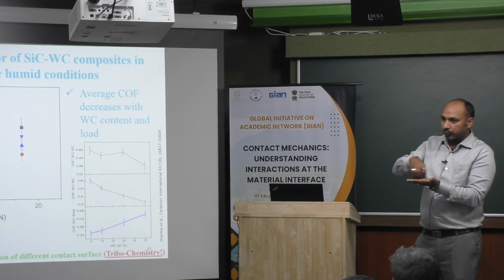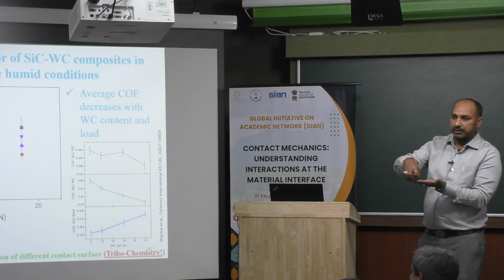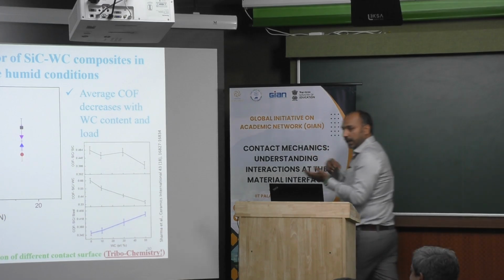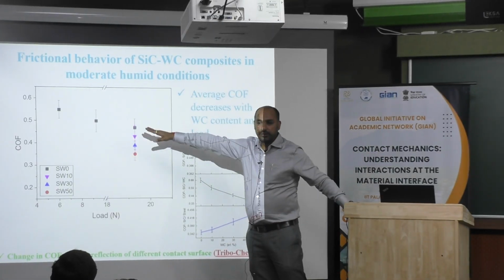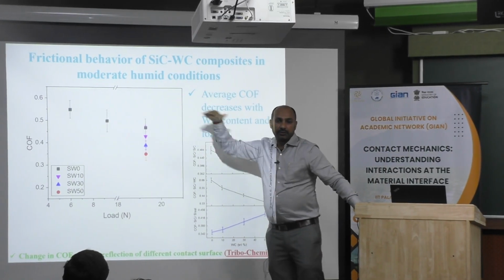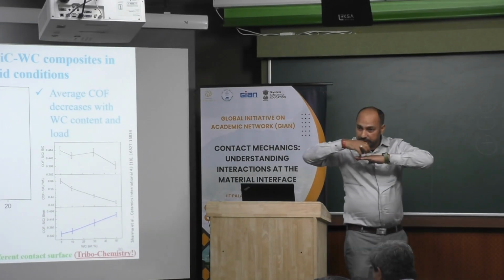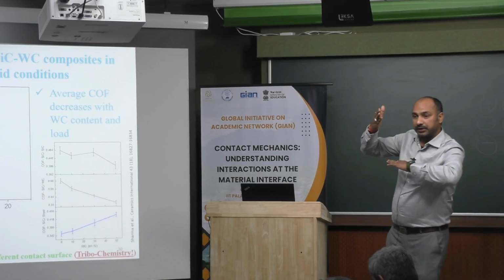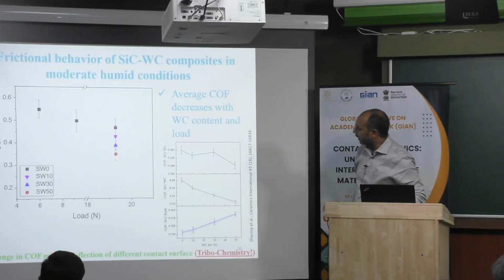But in reciprocating, contact time with the debris and the counter body is increasing. We are getting hard debris, so friction is increasing. Whether it will reflect in wear as well, we will see.